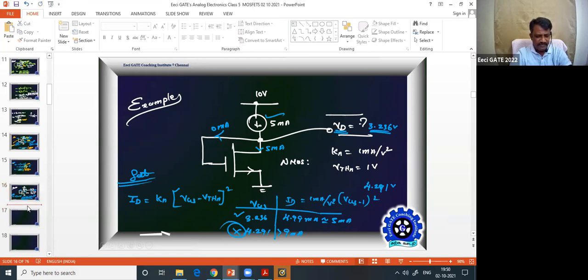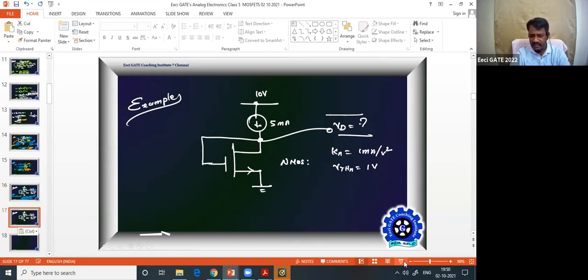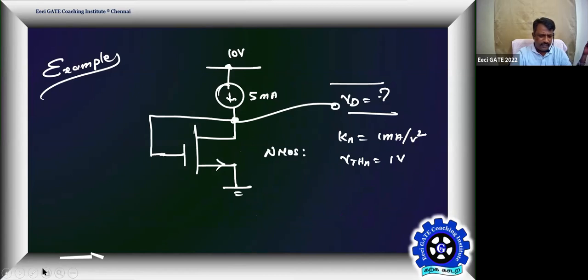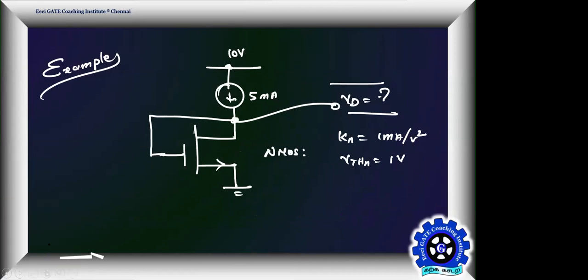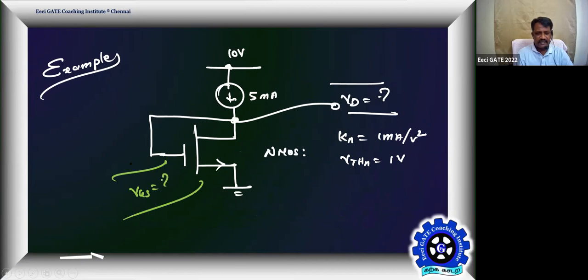Okay, try once again. I'll give the idea, Dinesh. Already it's a familiar route. Shweta, you'll probably feel familiar now. The route is very clear now, right? What is ID once again? Finding VGS. The current is very clearly known as 5 milliamps. Now let me check what route you played. The NMOS is clearly in saturation.